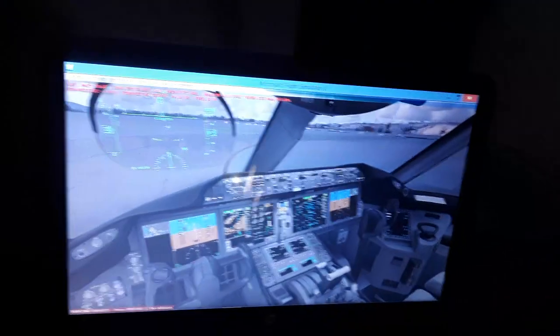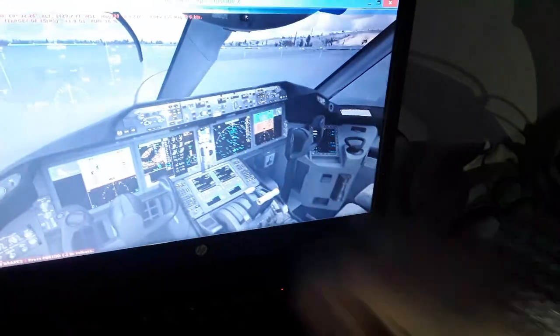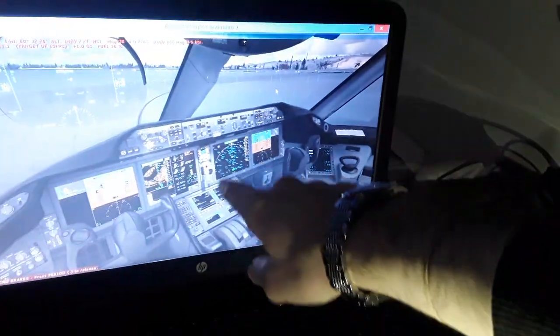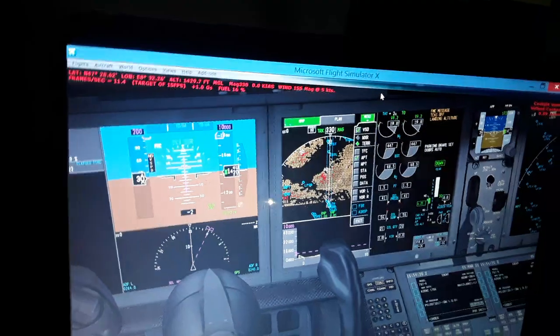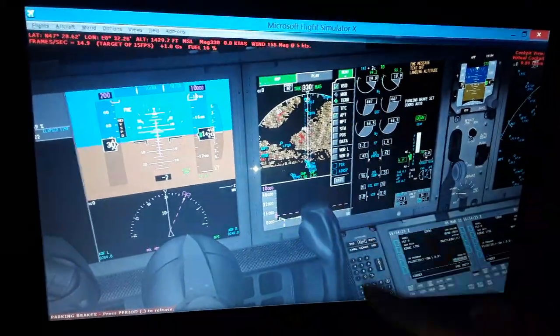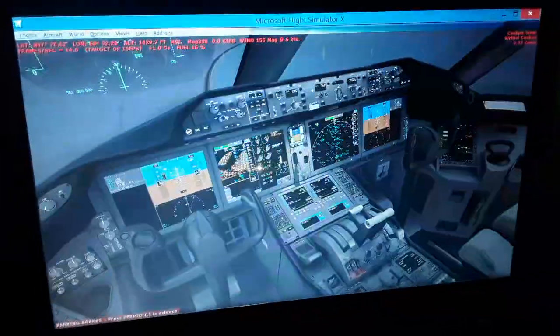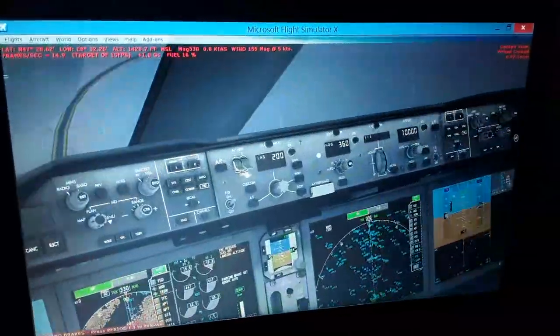We're gonna create a flight plan using the flight management computer over here. We'll input all the data that we need to create a flight plan. It is gonna be followed either manually or automatically. When we fly, we can connect the autopilot, so you will see from the flight management computer inputs. We're gonna create a flight plan that is gonna be displayed with the purple or magenta line here in the navigation display, and also in the HSI, and also in the navigation vertical display, in the horizontal, both of them. And now we can connect later the autopilot here, autopilot flight director system panel with the modes that you see.